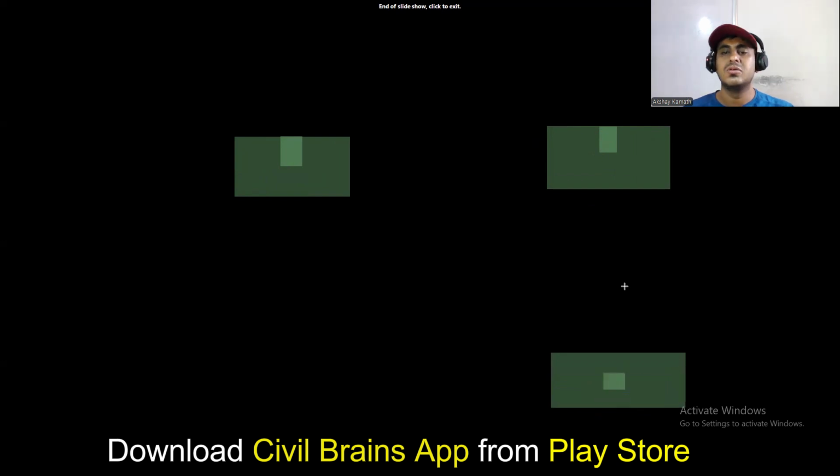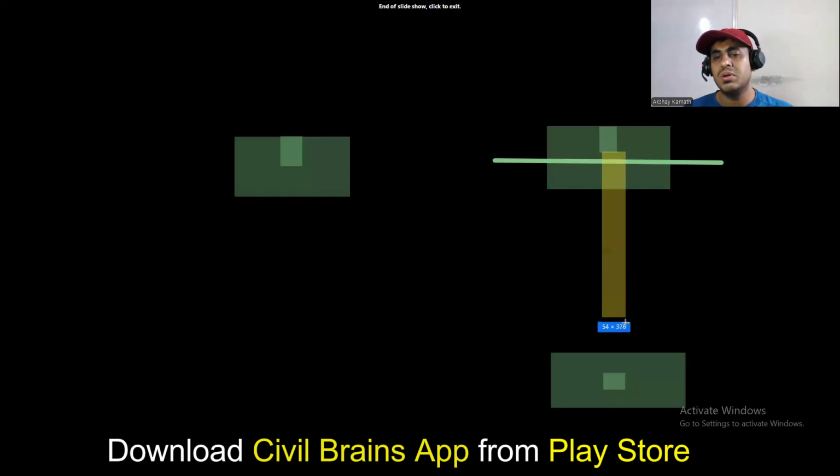Fine. So in which direction are you supposed to give a beam for this particular footing? Whether you should give a beam in this direction or in this direction. Very simple. Just see through which axis there is no eccentricity. Along the x-axis there is eccentricity, but along the y-axis there is no eccentricity, right? So wherever there is no eccentricity, in that direction you connect it with the beam. That's it. Because there is no eccentricity here, you connect your beam like this. Very simple. Understood the concept? Fine.